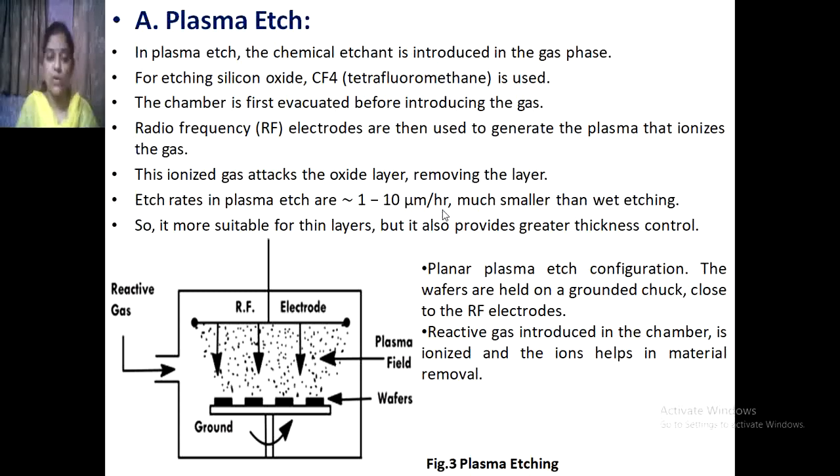So it is more suitable for thin layers, but it also provides greater thickness control. In the planar plasma etch configuration, the wafers are held on a grounded chuck close to the RF electrodes, close to the radio frequency electrodes.